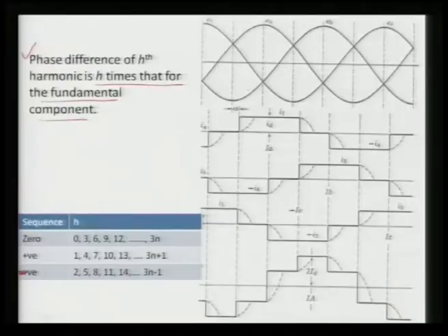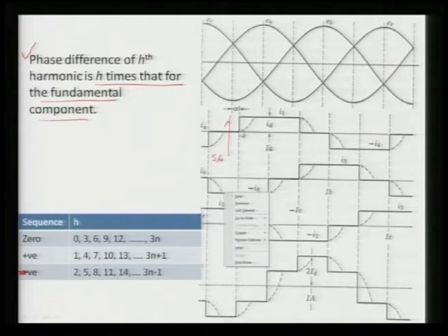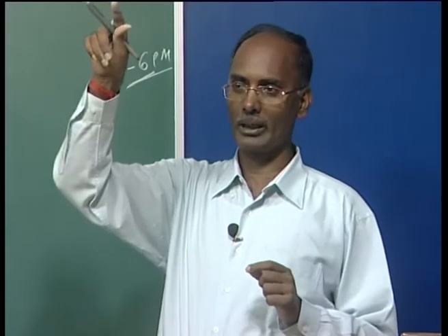Now, from this figure, these are simple phase voltages. At this point, valves 5 and 6 were conducting, because you can see the current 6 here, the lower one is 6. Now at this point valve 1 can be fired, because this is the commutation voltage of valve 1, that is EAC, because 5 is conducting, so C is coming.